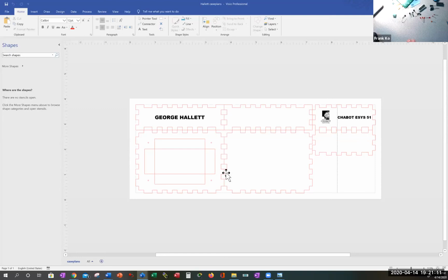Whatever image you want to put on here and pour it in, try not to use anything that has color. Try to use something that is only black and white, because the laser will cut black and white very, very well for you and give you a very nice image. If you paste something in here that's in color, yes, it's pretty for you and I to look at, but the laser won't know what depth to make the different colors. So do not put in a photo, for example, okay? Because that just simply does not laser cut very well.